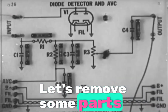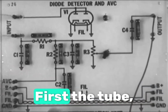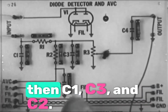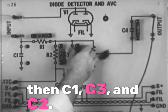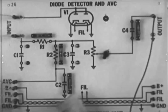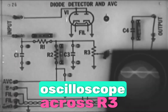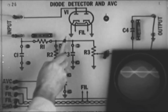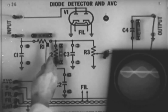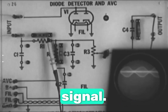Let's remove some parts so that we can see their effect as we add them back into the circuit. First, the tube. Then C1, C3, and C2. Now we'll connect the oscilloscope across R3. And move the second trace down so that we can observe the signal.